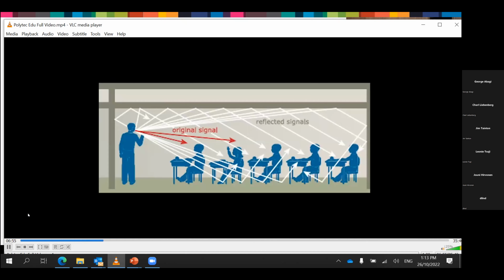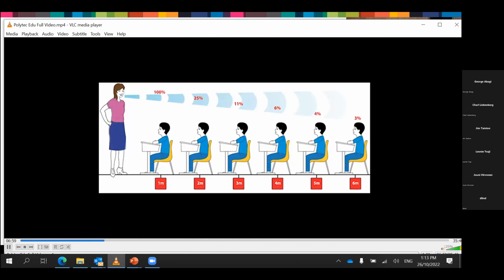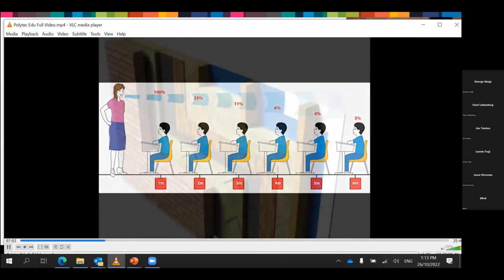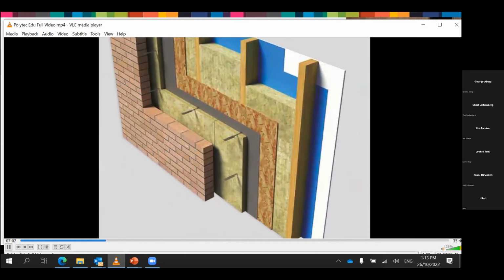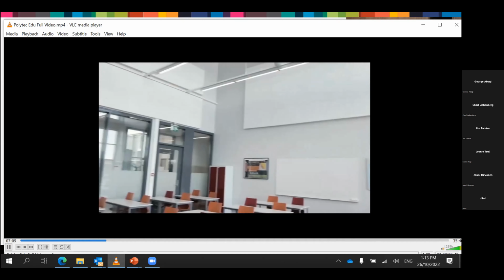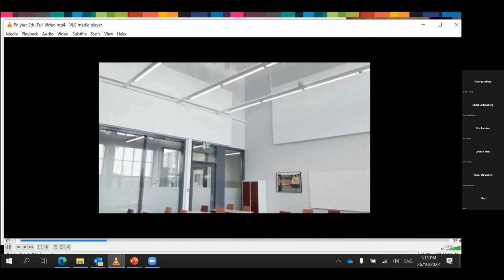Indoor environments, such as education buildings that are prone to generating noise, need to address acoustics as a matter of human health and welfare. Good acoustics in education buildings will, in most instances, mean high sound absorption. High sound absorption means less reverberation and a less stressful environment.